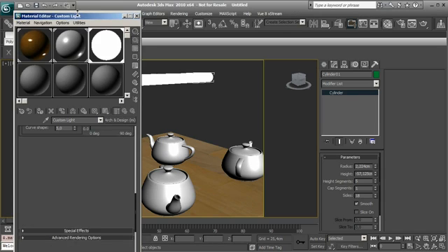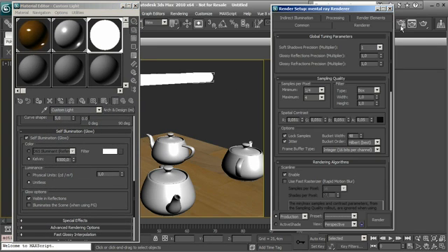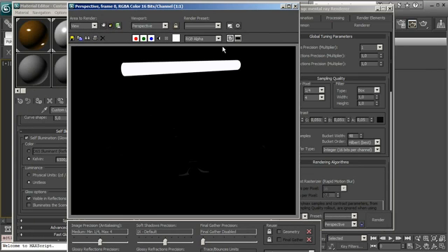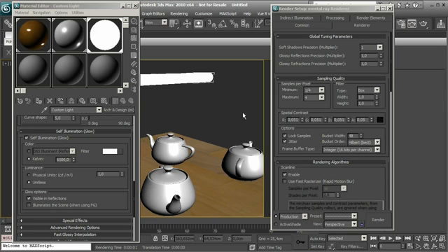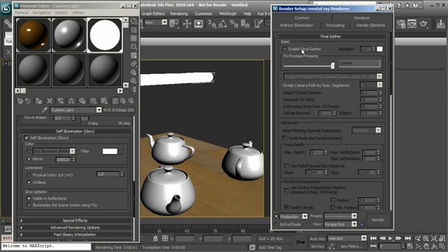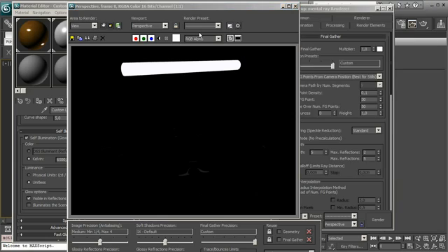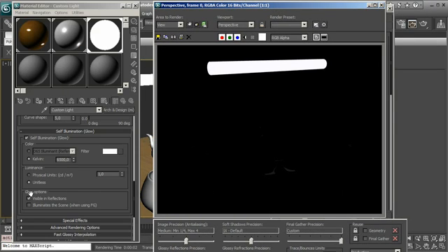and actually we can use the basic settings, and I can go there inside the rendering, and I can try to render a test, and you see that we have just this tubular self-illuminated, and we have just a reflection over the table. So to make the illumination, we have to set to on the final gather, and you see that if I try to render, we have no lighting, because we have to go inside the glow option, and you see we have the visibility and reflection, that is okay, but we have also the illuminate the scene when using Final Gather.